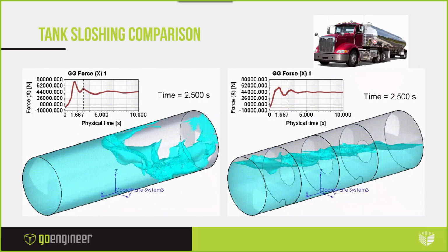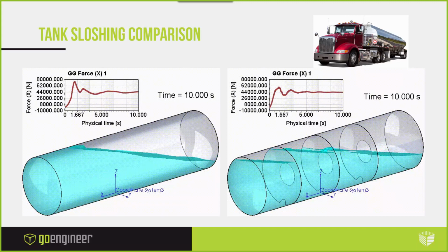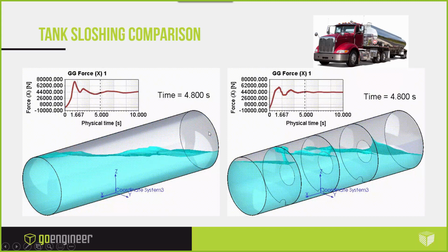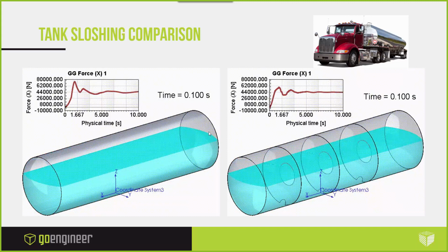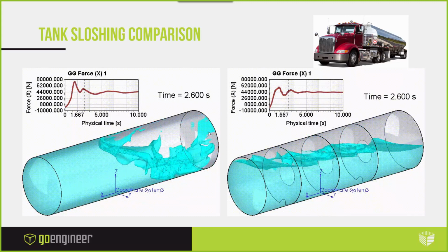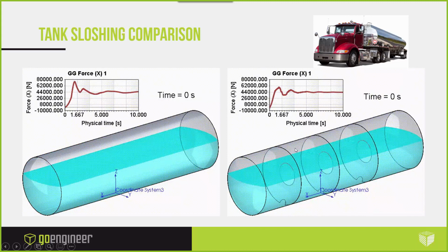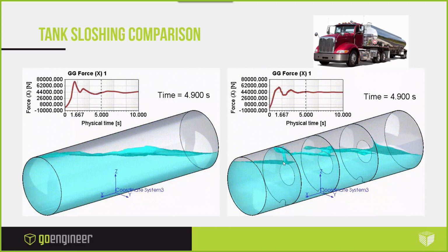So, I want you to consider a partially filled tanker in a braking condition. The liquid inside its tank will continue to move forward, slamming into the walls, like we see here, then sloshing back and forth in waves. So it begs questions like, how much force did that just apply on the tank in the X direction? Will it cause a dangerous pitching moment? Or potentially, how long will the waves last? Are they going to dissipate faster in certain baffle configurations or not? What is the best baffle configuration?